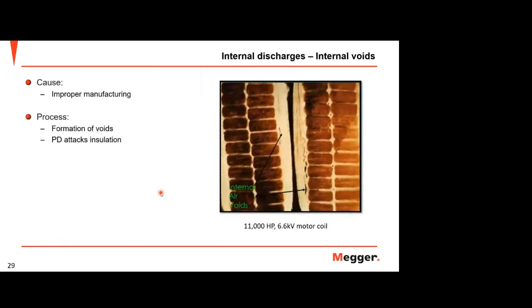Yeah, this is the internal discharge. If you see the stator winding like this, it is internal discharge, or we call it the internal void. Although manufacturing processes are designed to minimize the internal void, in fact there is some void content that still exists.